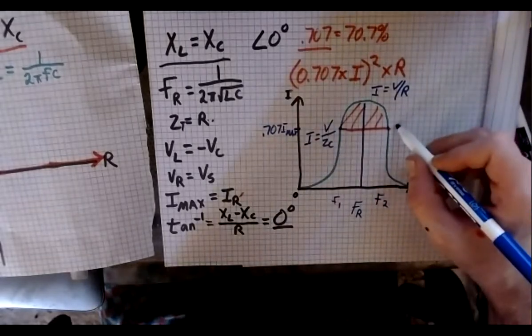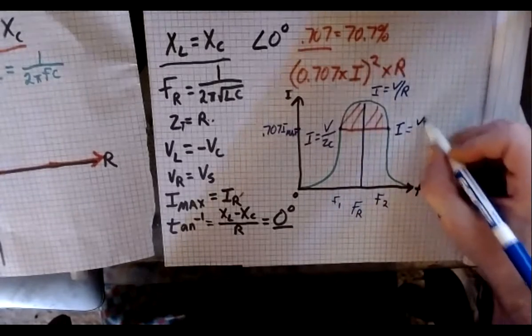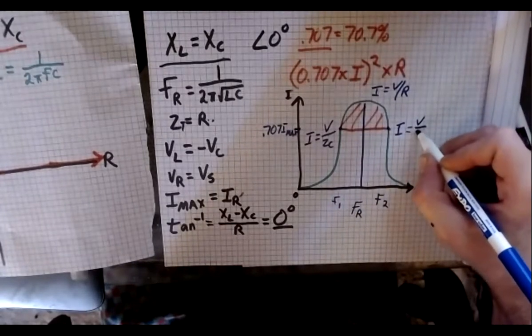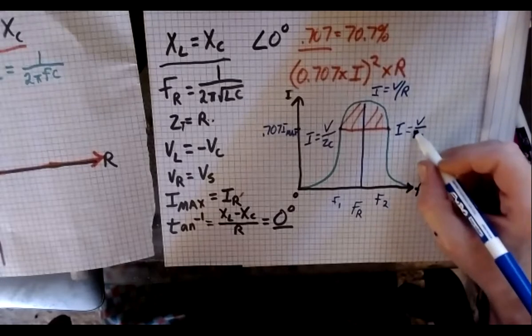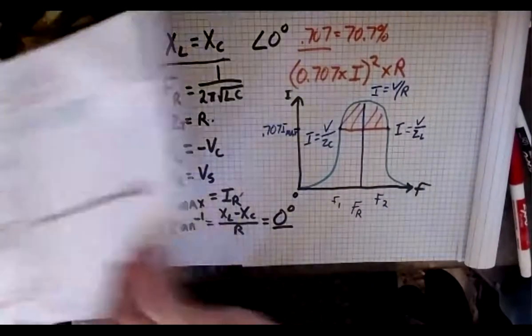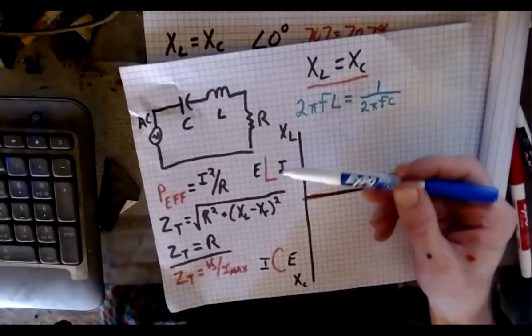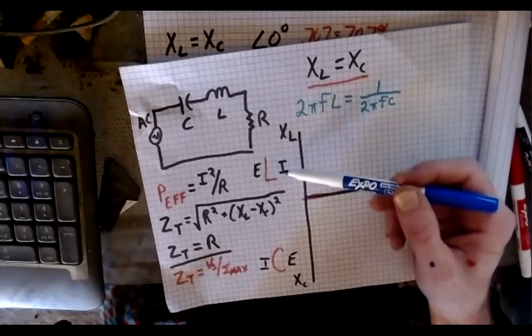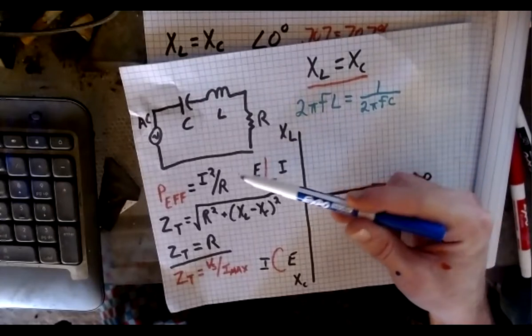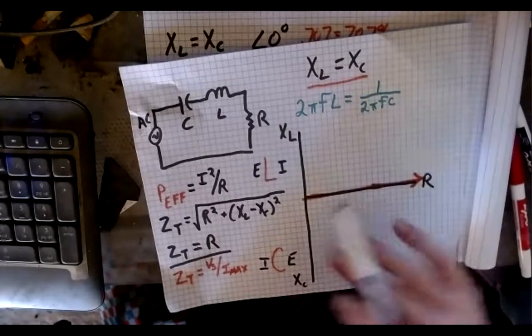And of course, on the other end of the coin, as we start going up, the circuit starts to become more inductive. Now, based on our original, right? As we start becoming more inductive, the voltage is going to start pulling ahead of the current curve. And now my circuit's not going to be so efficient anymore.